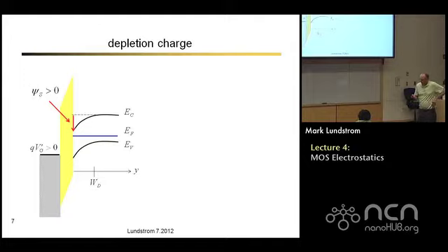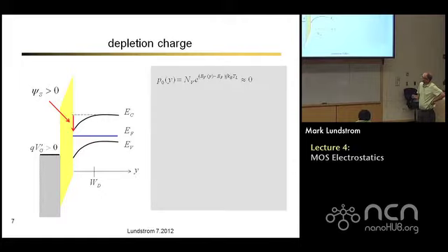All right, so there are a few things that I need to discuss. The semiconductor was doped p-type. And that means there are a lot of empty states in the valence band, and the density of holes is significant when the Fermi level is close to the valence band.